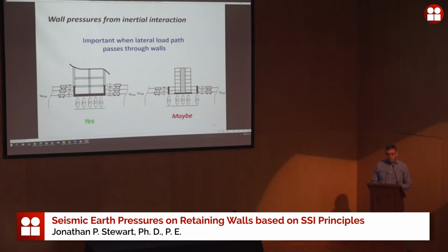This is a very common situation with tall buildings in California, maybe here in Mexico too, where if you have a tall building, you will often have a shear wall near the middle of it, which is the principal carrier of lateral loads. And that shear wall doesn't stop at the ground line. It goes all the way down to the foundation. So you have a continuous load path down to the foundation. When you get below the ground line, so this is the ground line here, right?